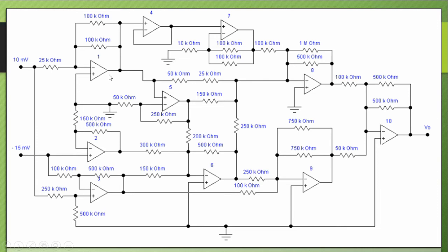For number 1, what type of op-amp is this? The input is connected to the negative terminal, although there are two resistors here. These are just two resistors in parallel. We just have to get the equivalent resistance here. So this is an inverting op-amp.